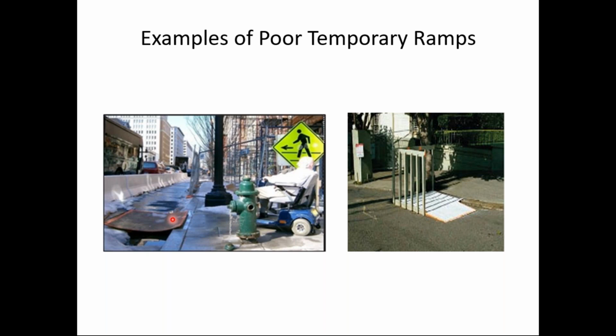But then further here, I like the way that somebody maybe got a skid steer or something in here, and it looks like they tried to clear the snow from the pedestrian access route. That's a good thing. But on the other hand, notice they didn't clear it from around the base of the ramp. And maybe they didn't because there's not 5 feet there for someone to turn. So this is a turning space at the base of the ramp. In this case, because it's constrained, it needs to be at least 5 feet in the direction of travel. To me, that looks like 2.5 or 3 feet. Maybe that's why they didn't clear the snow, they knew nobody could turn there. But that's a real issue. That basically makes this ramp unusable if somebody can't turn to continue on the walking path once they go down the ramp. So a lot of things to consider in that image.